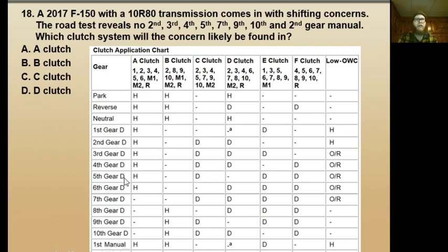So let's see what's on in second gear. Got these for the low one-way clutch there. In third, fourth, fifth, skip sixth. Oh, so that takes the A clutch out, right? Because that's on in sixth, but sixth works somehow for us. I don't know how we got there. Must have had a nice hill to go down or something. Seventh, yeah. Eighth, well, that wasn't even in play to begin with. Ninth. All right, so I think we have our culprit here, which is clutch C.